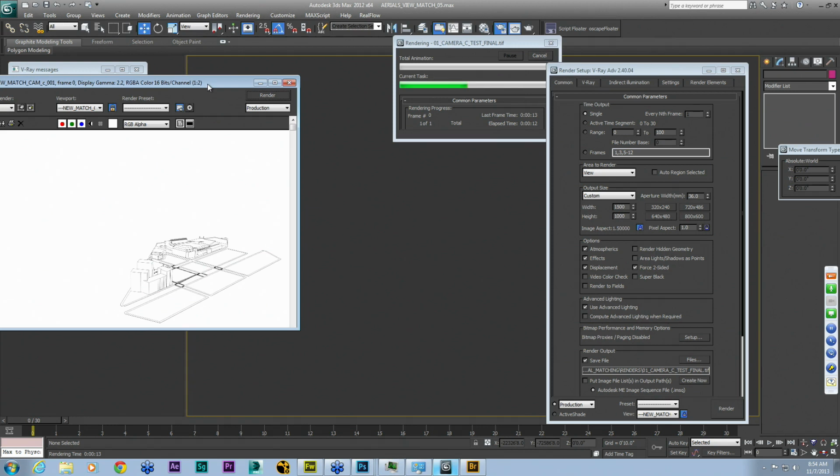And the one thing you will learn with view matches is that definitely the most important thing is always the foreground, or what you're actually view matching. And as it goes back in distance is where you're going to get discrepancies, even if you build context models, just because whatever you build in Max, especially if you're using a projection map like a Google map, is not exactly accurate. And those inaccuracies will get exponentially larger as you go back in distance. So trying to use things really far away to line things up makes view matching a lot more difficult than using the things in the foreground.